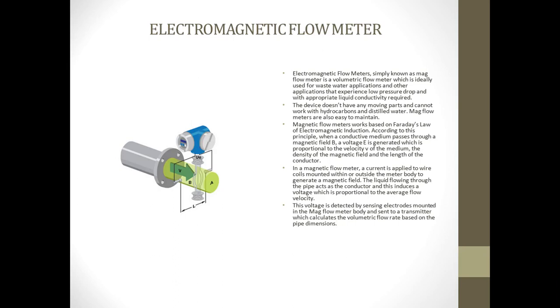Few of the disadvantages are: number one, conductivity of fluids must be higher than a certain minimum required level. Number two, the meter must be full at all times because it sees velocity as analogous to volume flow rate.